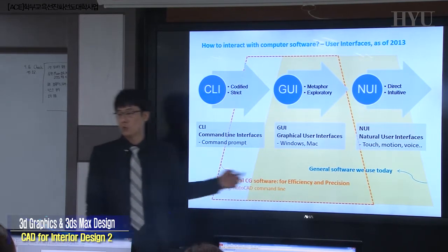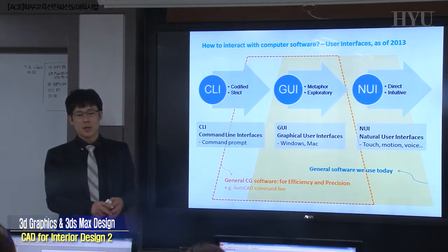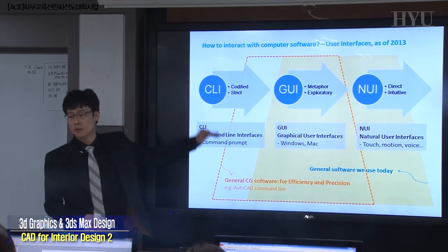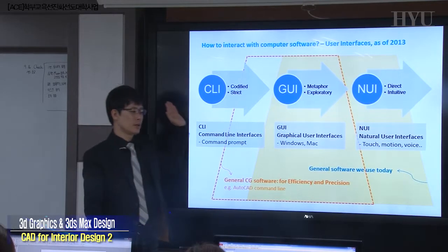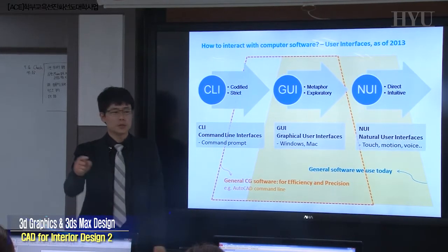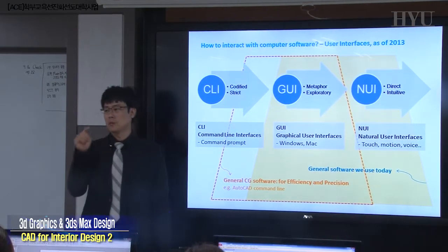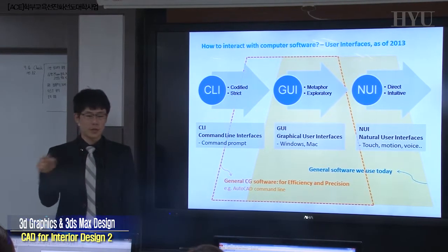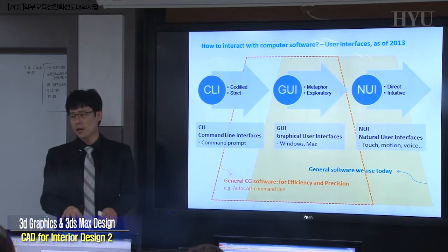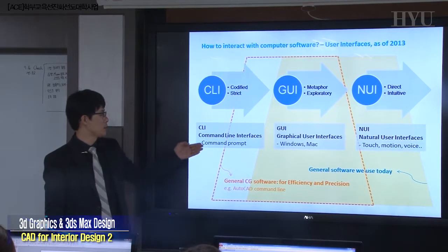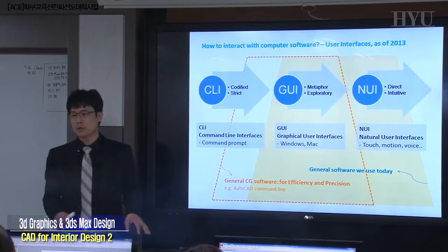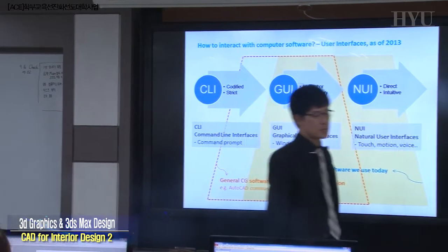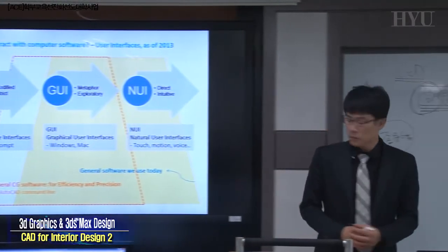So that is why we need to type command lines. Just imagine there is no command line in AutoCAD, only toolbars. You would have to click trim, line, rectangle, every time. Just clicking and typing, clicking, typing. But if you have a command line, you can save your time. Just type TL, L, E, O for offset, and so on.